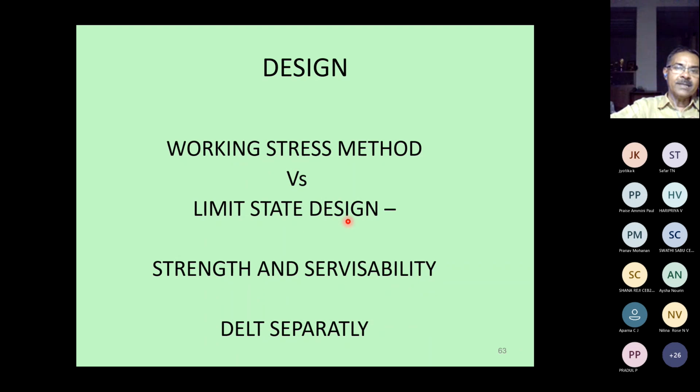Now in the case of limit state design, which has later come into all design fields, you might be studying concrete, steel, pre-stressing, everything in the limit state design. Of course, the soil or the foundation designs are still in working stress method, but soon the IS codes, which are under preparation in draft forms, are going as per the limit state design for the soil also. We split our factor of safety into two, and one part is applied on the loads, the other part is applied on the material.